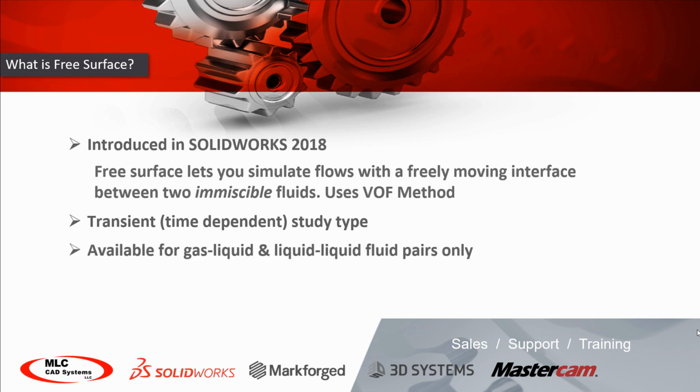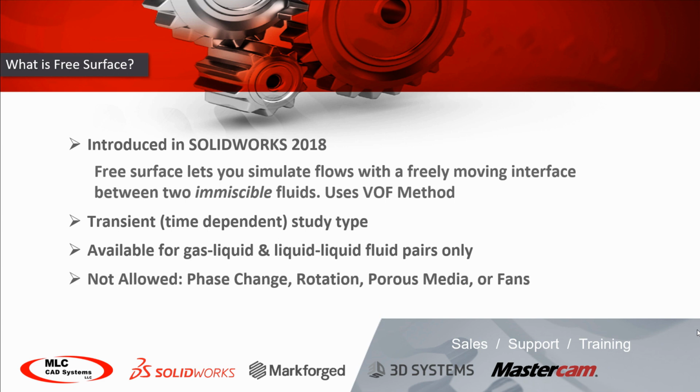This is also available for gas-to-liquid or liquid-to-liquid fluid pairs only. Luckily, that's about everything we work with, but you couldn't use non-Newtonian fluids here, or, say, a real gas model or steam. In this case, it's just gas-liquid or liquid-to-liquid immiscible fluid interfaces. What's not allowed is, of course, phase change. But some of those advanced options you might turn on as well, like rotation, or a porous media, perhaps to represent a filter, we couldn't do that. We couldn't run fan models, and humidity or cavitation models also wouldn't be turned on in this type of setup.